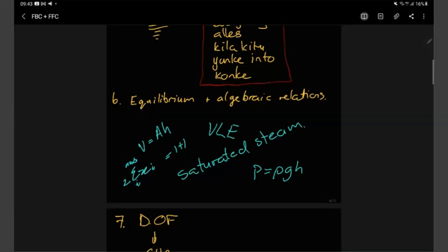Right, so v equals, these sort of equations are the ones that relate our mass and energy balances to more specific variables that we can isolate. So in the event that we're controlling level, we don't want to work with volume because it's not the direct variable. Level is the height of the thing. So height times area is obviously volume.